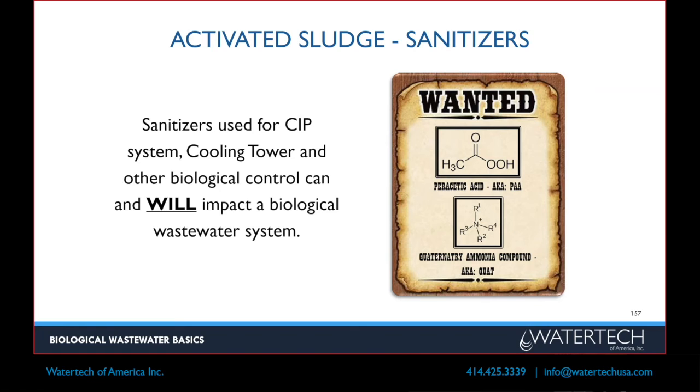We just had a customer municipality, one of their customers, which was a cheese plant, dumped half a 55-gallon drum of PAA down the drain, and I think it's been 3 weeks and it's still not back to where it should be. Wow. Yes, these are very aggressive biocides, very good at what they do. That's why they give wastewater plants lots and lots of issues.